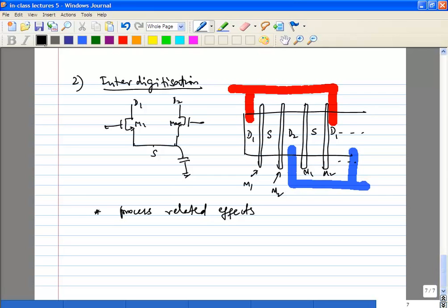If you just lay it out as two huge blocks and you don't know which way the wafer is going into, let's say, the furnace, there will be temperature gradients. Similarly, if they're doing some deposition of the dopant, it will come from a certain direction. It may not be uniform. Those are all things you have to worry about when you want matching.